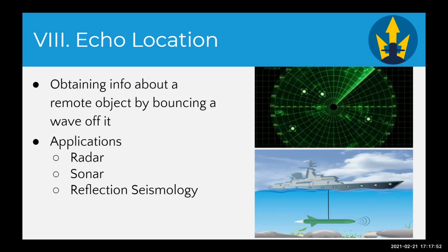In the case of sonars, it stands for sound navigation and ranging. DSP has revolutionized sonars through pulse generation, pulse compression, and filtering detected signals. In active sonar, sound pulses between 2 kilohertz and 40 kilohertz are transmitted in the water, and the resulting echoes are detected and analyzed. In passive sonar, we just listen to underwater sounds, which can be marine life or mechanical sounds coming from submarines or vessels.